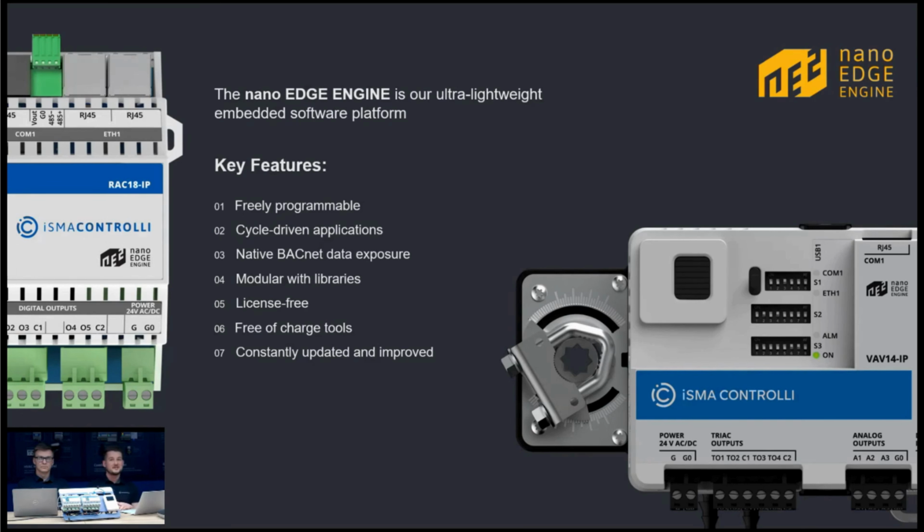First of all, it's fully programmable and it's based on cycle-driven applications. That means you can create applications using logic blocks and a wiresheet, and you can drive not only one but multiple applications in time cycles. Those can be different time cycles for different kinds of applications, even on the same controller.